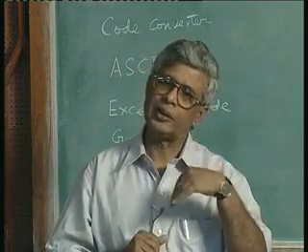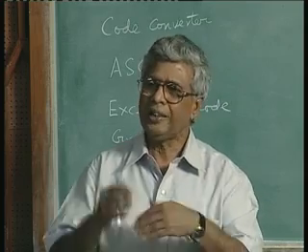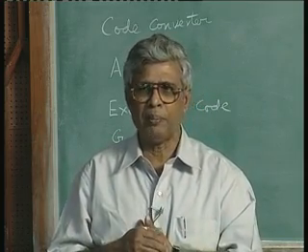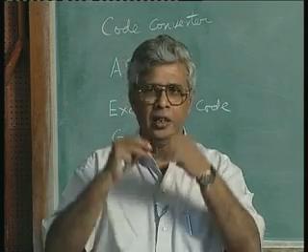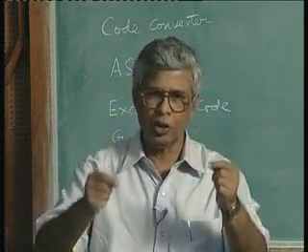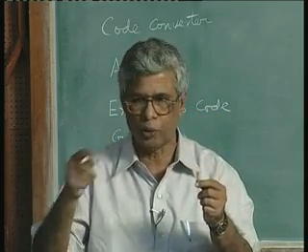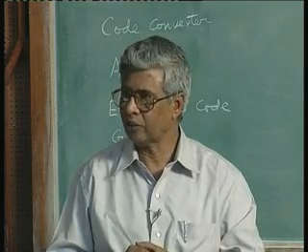The third one is the switching activity and power saving and all that speed activity. That is the Gray code. These are only some examples I am giving you, a few examples. A representation of a number using zeros and ones need not follow the sequence we are used to. 0 is 0, 1 is 1, 2 is 1 0, 3 is 1 1, 4 is 1 0 0, 5 is 1 0 1. This is called the natural binary sequence, the normal binary sequence.